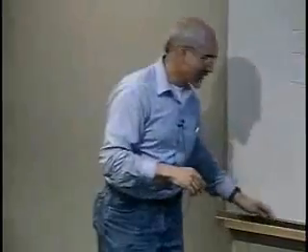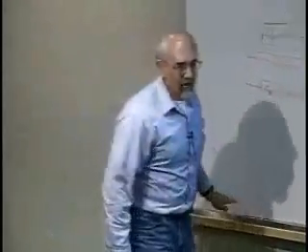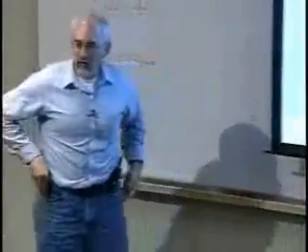If you abide by those rules, it's all a linear system and you can apply all these techniques. Once you go outside of those rules, you need some other creativity to deal with it. Typically we do a multi-state kind of analysis and divide the system up into regions in which they're linear. There's a technique called gain scheduling that uses that kind of notion as well.